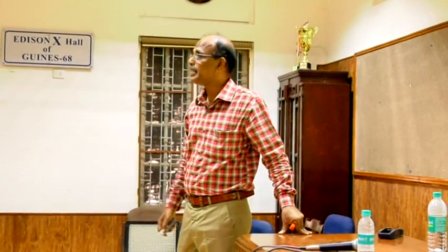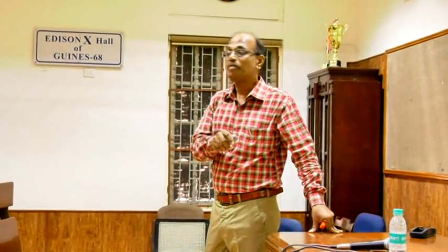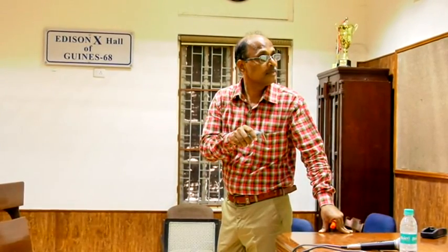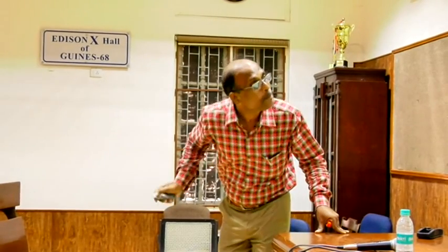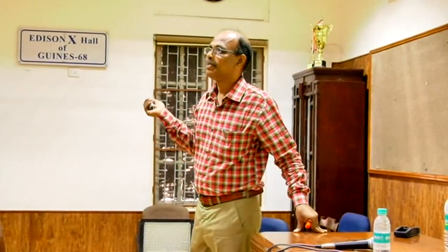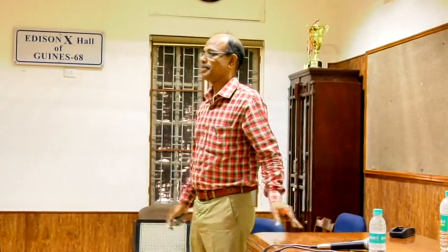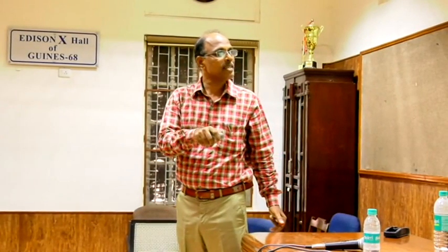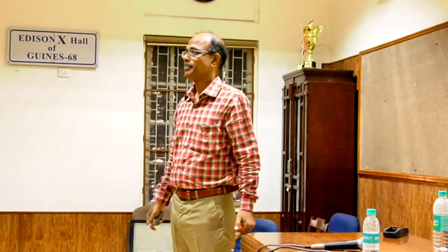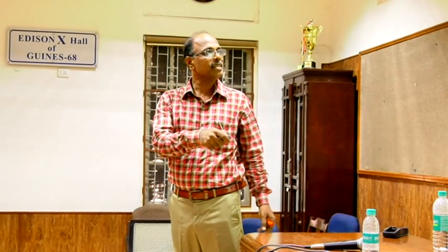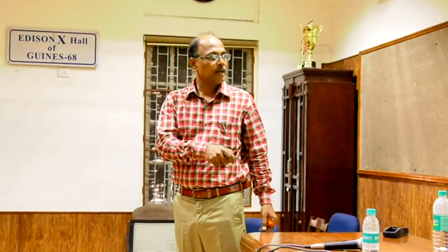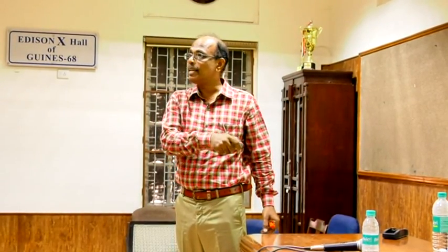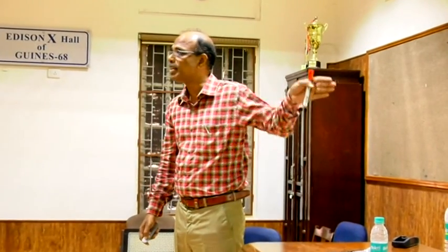The system has 13 buses, out of which there are 5 generators and the remaining 8 load buses. 13 minus 5 is 8. So here there are 8 load buses and 5 generator buses. Let us consider this system. Let us consider this is the slack generator. So P1 is the slack generator. The rest are the buses. So I have sorted all the variables.